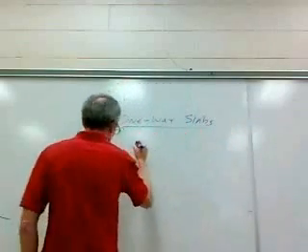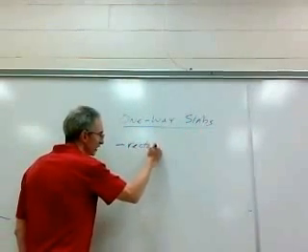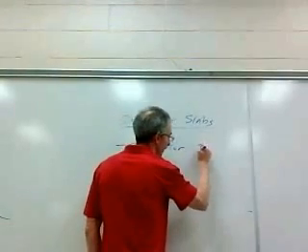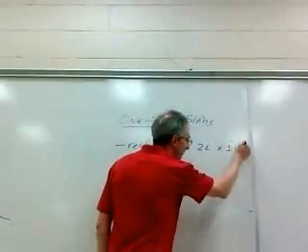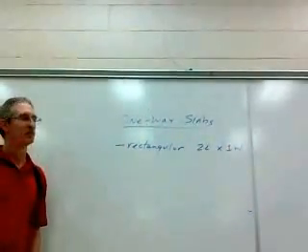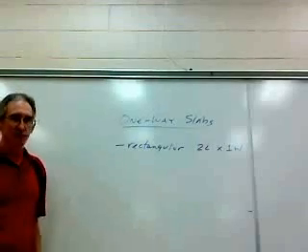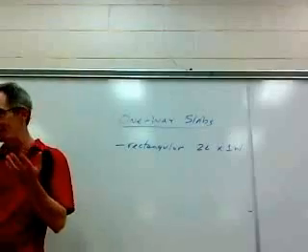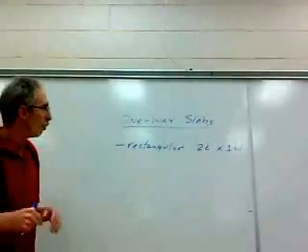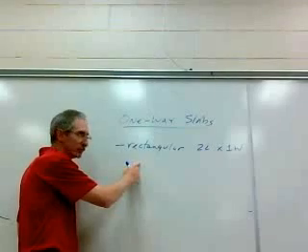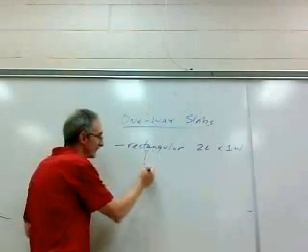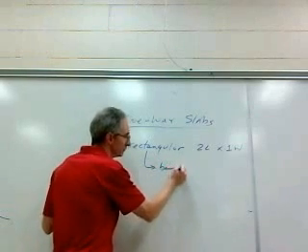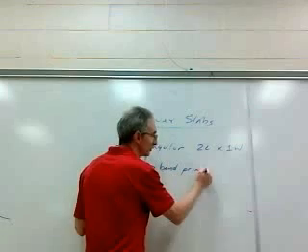One-way slabs are generally rectangular slabs. And that means that they're twice as long as they are wide, at least. Okay? So when you look at the perimeter of how a slab is supported, it's generally going to take the shape of a rectangle. What a rectangular shape will do for us is that these slabs bend primarily in one direction.